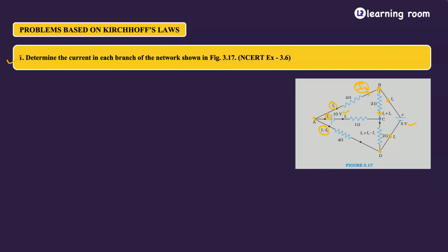So this I2 is reaching B. That's the first point. This I1 minus I2 is coming here, and from it I3 is getting split. Let's say I1 minus I2 is 4 ampere. I don't know the value. Out of 4 ampere, let's say 1 ampere is getting split here, and the remaining 3 should flow like this. Instead, what they have done is this I2 is combined with this I3. So I3 is taken in this direction, and I2 and I3 are going towards this junction. What will be the current leaving the junction? I2 plus I3. That is why they took this as I2 plus I3.